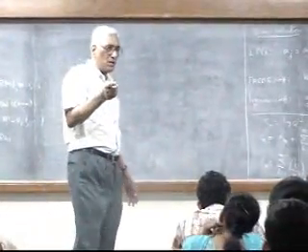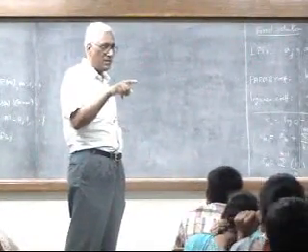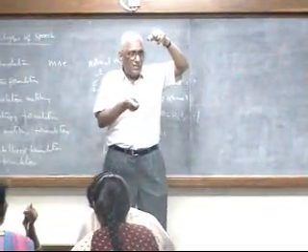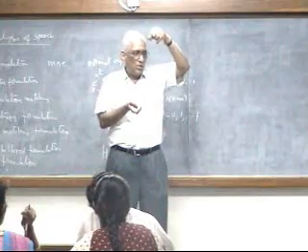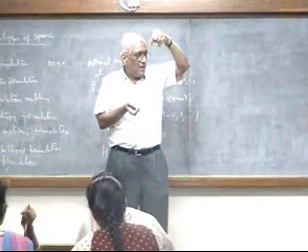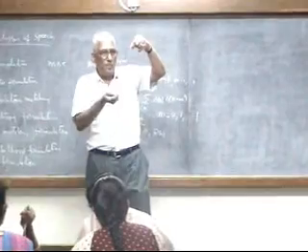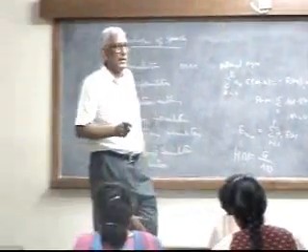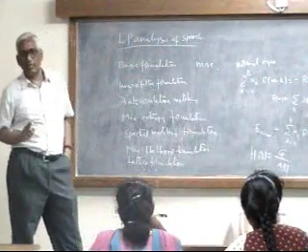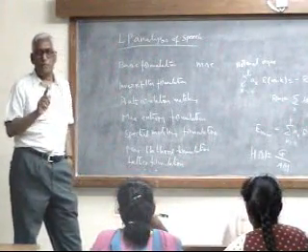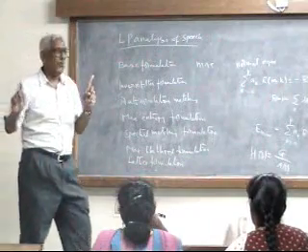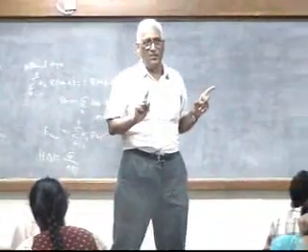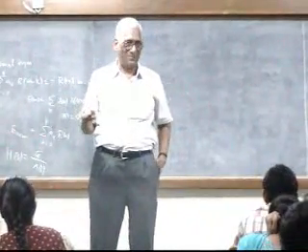So it has to be outside the origin, all of you understand what I am saying. In the Z domain, you have to understand, if it is not at the origin, then it has to appear as a pair. So if that appears as a pair, if there are p roots, it means a maximum of p by 2 such pairs will be there. So you decide a priori. If p is equal to 10 or any p you decide, you can only put p by 2 peaks, and where to locate these peaks and what width these peaks should have is dictated by the envelope of the spectrum.